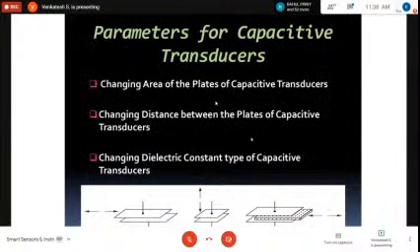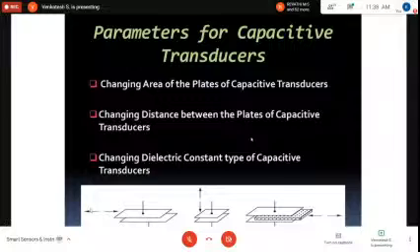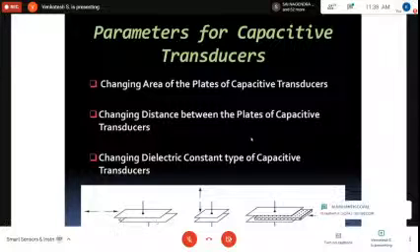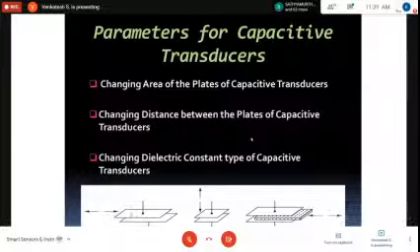Now, if I slide the above plate with respect to the fixed bottom plate, in diagram A, please observe the cursor, as the upper plate moves away, the overlapping area reduces. There is some extra plate on the top plate there. The overlapping area is our only concern, which produces some capacitive effect, because there is no equivalent parallel plate here.